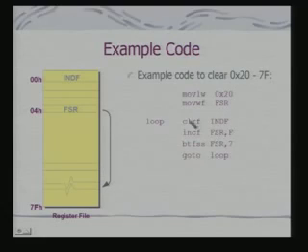Now, we are clearing INDF. Okay. And then we are incrementing FSR. F actually means the result will be set back, and then we are going through this loop. Now, the interesting feature you should note here is how actually the clearing is taking place.